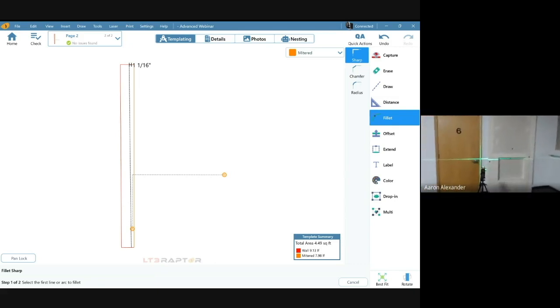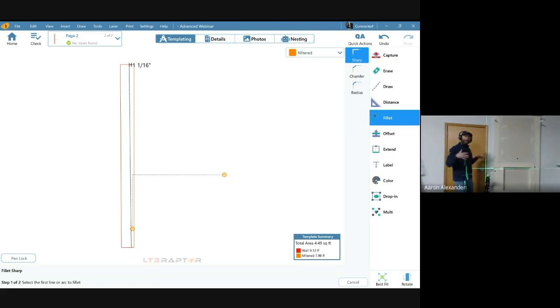Okay. But as you've seen there, I always say, you know, spreading this stuff out as far as you can is the preferred method. But again, your eye's ability to aim the laser directly affects our accuracy here as well. That thing was pretty far away. The ceiling shot's pretty high, and that shot was pretty far away, and I really didn't do a good job aiming my laser at it. So I brought it a little closer to me. I was able to aim my laser better, and I got better results there, right?